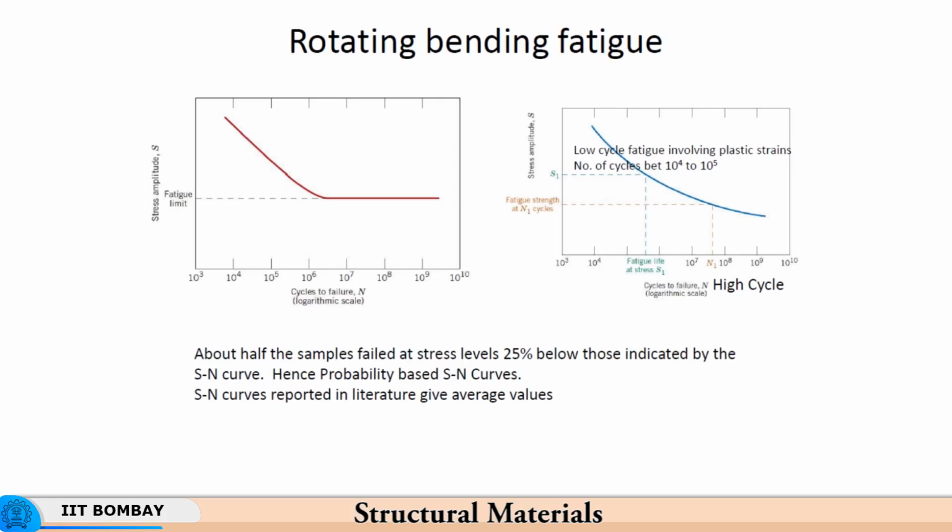This way the fatigue loading tends to accumulate strain during rotating bending, and this accumulated strain can also result in accumulated fatigue damage. That is the reason why, as you increase the stress, the stress amplitude required for damage decreases. So, for higher stresses, the number of cycles of fatigue damage is lower.